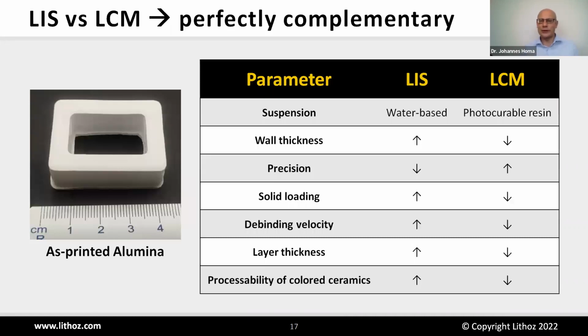You will see afterwards some examples, but here once again some differences. So with the LIS, we have a water-based slurry, which is close to slip casting, and this is, I think, also a good thing which we have now for the ceramicists, where you can also develop your own slurries much easier than with the photocurable system, because ceramicists are used to working with these kinds of water-based systems. So I think this is one of the advantages of these systems.